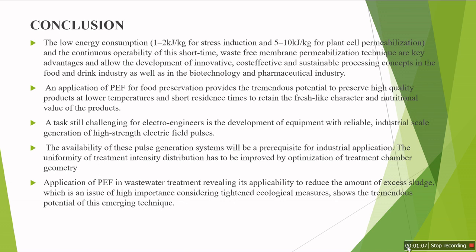The uniformity of treatment intensity distribution has to be improved by optimization of treatment chamber geometry. Application of PEF in wastewater treatment, revealing its applicability to reduce the amount of excess sludge, which is an issue of high importance considering tightened ecological measures, shows the tremendous potential of this emerging technique.